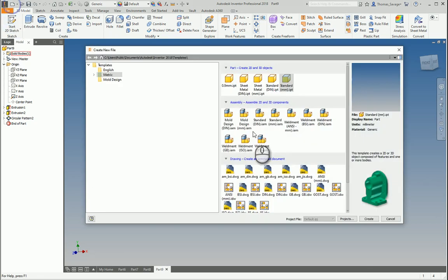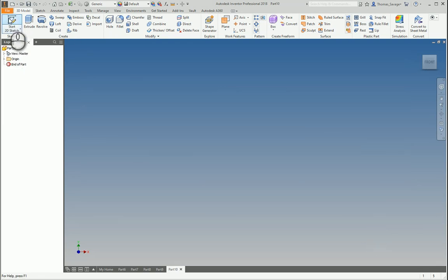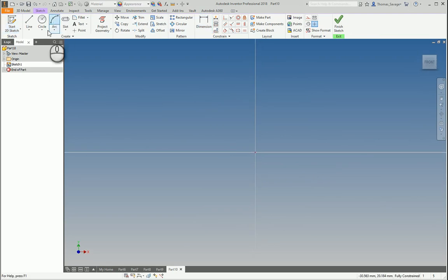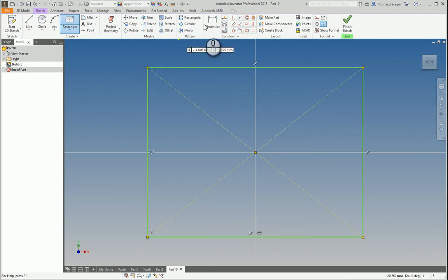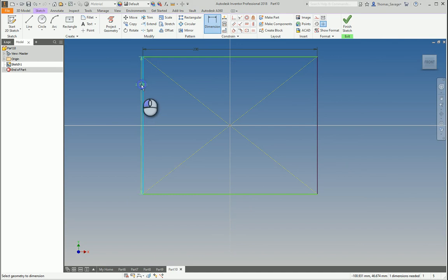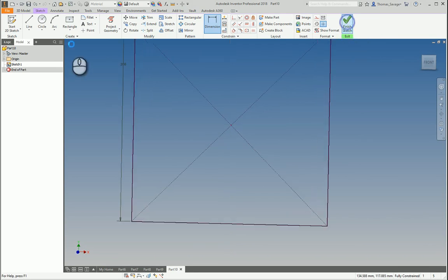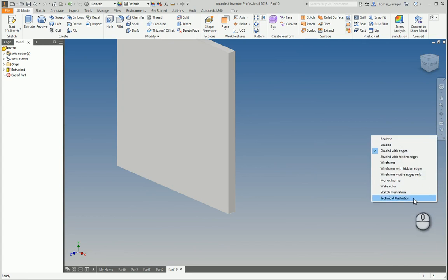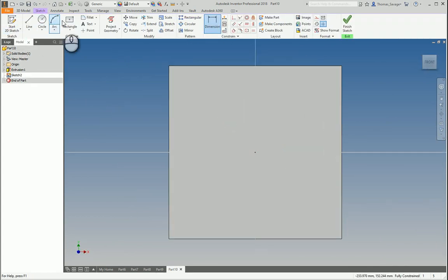Now we'll look at the mirror feature. I'll show you to mirror a cut, which would be a good place to show how it works. So if we add a fully constrained extrude. Okay. Now if I place a cut, it doesn't have to be a cut. I'll do a cut and like an added on piece that we want to mirror over.